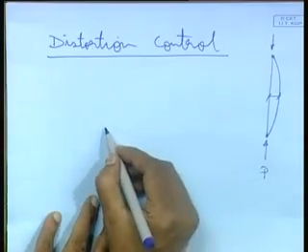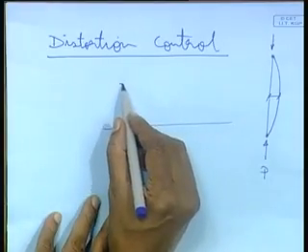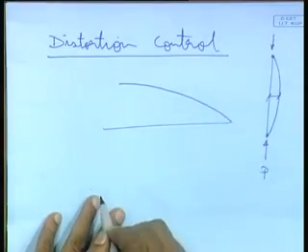Apart from corrosion, the hull is wavy, so it may add to your so-called hull resistance, because the flow pattern may change from laminar right at the front, it may become turbulent, because the hull is expected to be smooth.